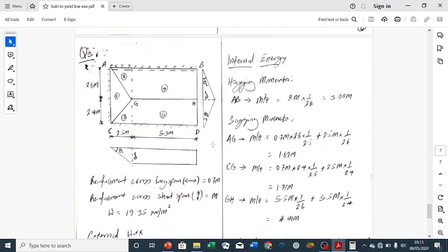The next thing we do is to calculate the hogging moment. We have one hogging yield line, hogging yield line AB. So this is how we calculate it. This is hogging yield line AB. Remember, for this hogging yield line AB, the reinforcement that will resist it is a vertical reinforcement that will be going like this. The vertical reinforcement, and we are told that vertical reinforcement has a value of M. We were told that in the question. So take note of that.